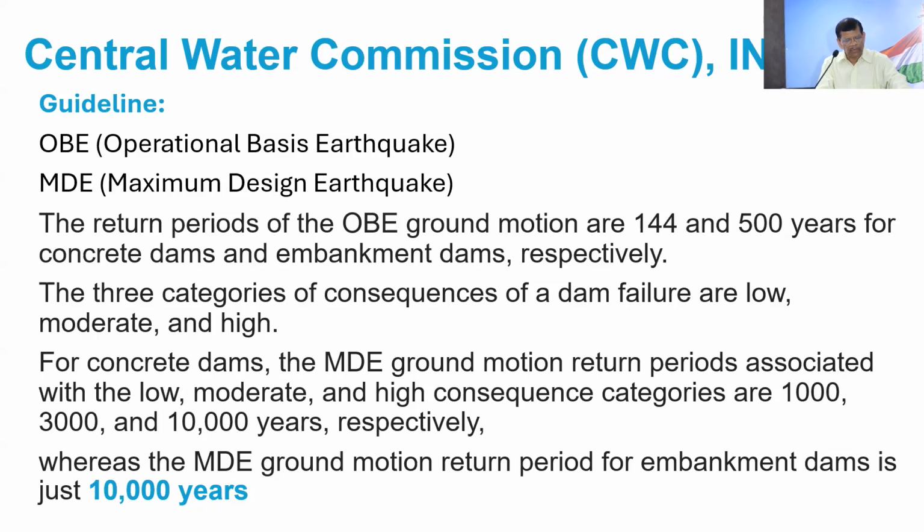So two important events we always consider. We call them OBE, operational basis earthquake, and MDE, the maximum design earthquake. What is the difference? One is during the operational time, because operational time is short.